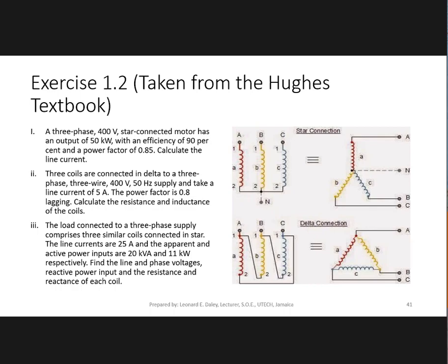All right. So couldn't you just find resistance by dividing the line voltage by the line current? No. Can't find resistance like that. If it was a purely resistive load, you could do that. But from what they tell you, it's a coil, and the coil has resistance and reactance, right? True.